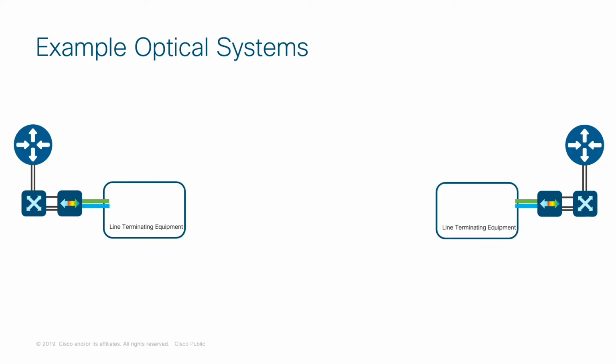We then take all of those different colored lights and we put them into a system called line terminating equipment, where we'll have what's called a multiplexer. The multiplexer basically combines all of those different colors together into one beam of light. And it does this typically using very accurate optical elements. Now, there are some other pieces in the line terminating equipment to make sure that the signals are nice and equivalent and everything is combined together.